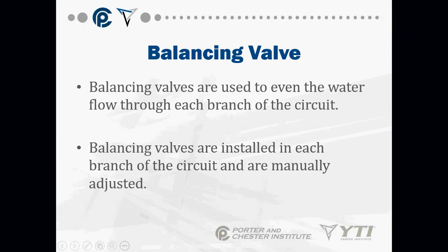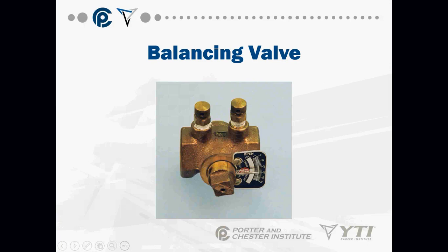Okay, balancing valves are going to be used to even the water flow through each branch of the circuit. Balancing valves are installed in each branch of the circuit and are manually adjusted. So this is what that would look like.